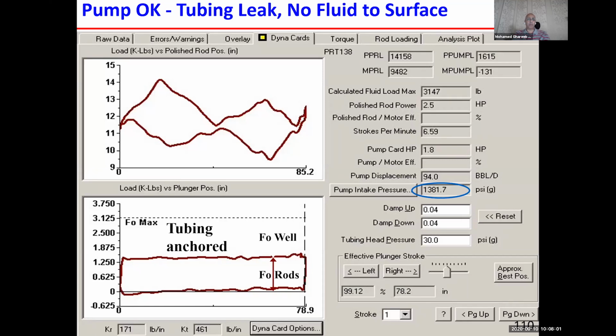What we have now on the screen is a real dynamometer card. One card from one well: what is measured is the surface card, and based on that, the downhole card is calculated. Based on this downhole card, if someone looks at this, he says, yes, the pump works almost ideally. You have a very good shape of the card. That means I produce completely the fluid that the formation can give to me. Yes, you are right. But I inform you, when you are analyzing the cards, do not look at one point, do not look only at the shape of the card.